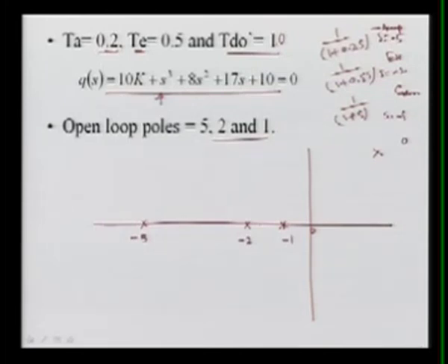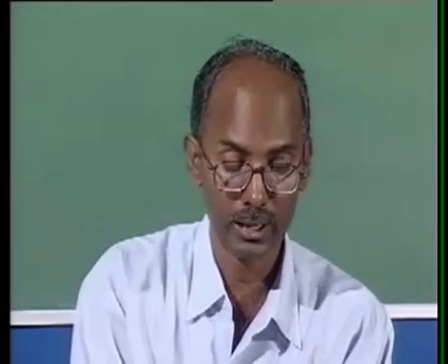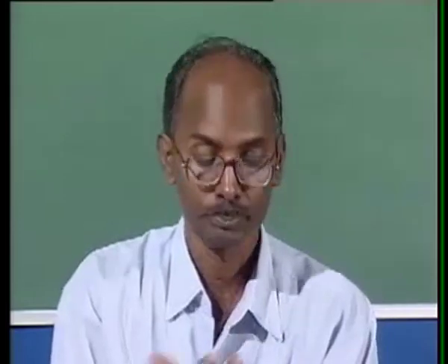Now you know there are various rules for the root locus and the movement of the roots. Let's suppose k is 0; if you solve, we get these open loop poles. So when k is 0 we are starting at this point, here also k is equal to 0, and at this point also k is equal to 0. But we want to change k from 0 to infinite, and then we will see how they change. Once k is 0, they lie here, at your open loop poles.